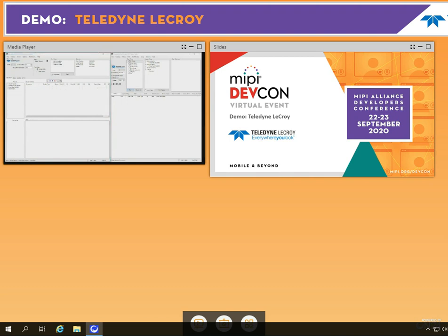The Envision X84 can also generate full image frames. When used in video mode, the user defines the packet format, the frame timing, the resolution, and either a .bmp or a .bin image. The X84 will generate all lower level traffic automatically to generate the frame.